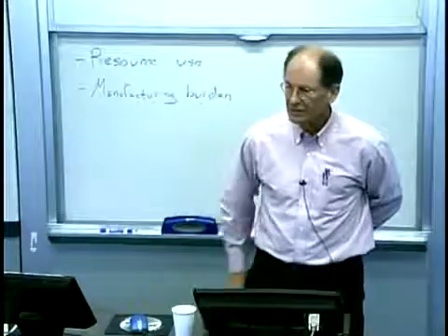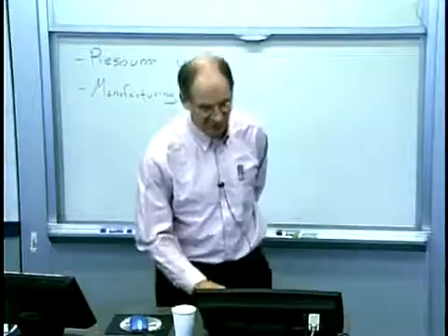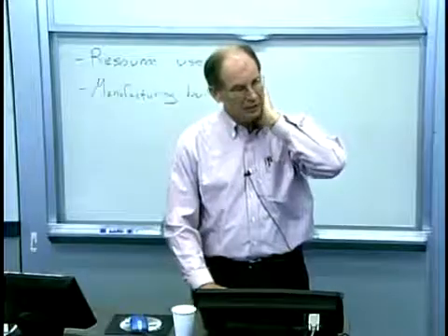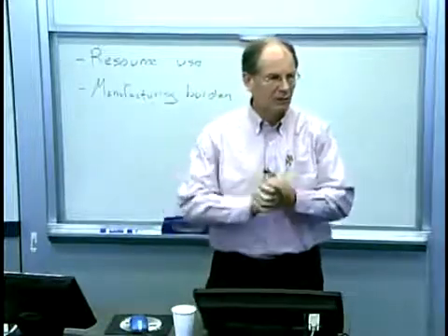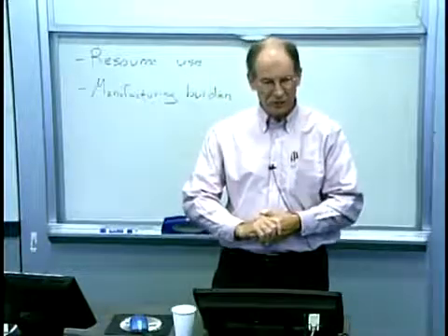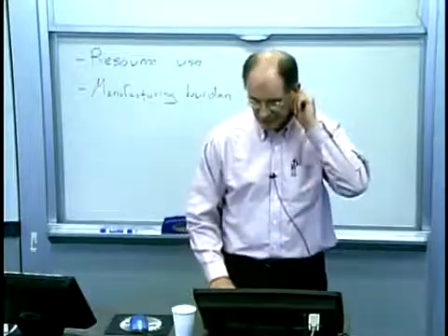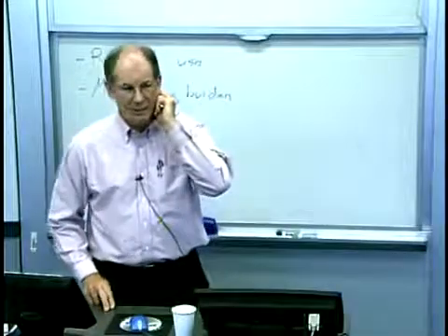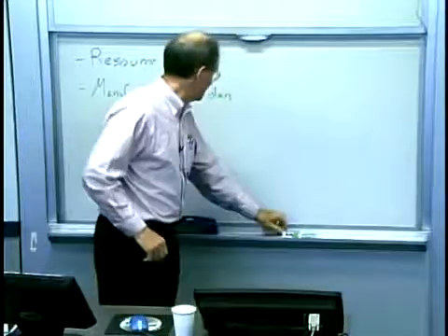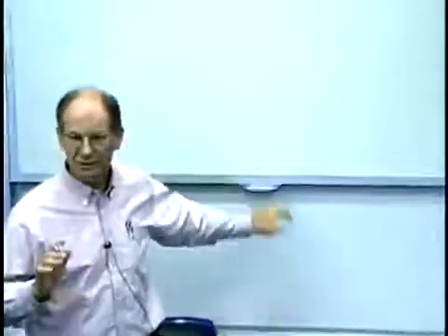So the hypothesis, in effect, or the approach, is to basically say all processes have a certain degree of randomness. And this idea of assignable causes, which, if you're from a control systems background, would be disturbances or changes. If they've all been eliminated, then it is a purely random process. So this concept of common causes, or again, purely random effects, if that's all that's left, then you do indeed have a process that is in a state of statistical control.